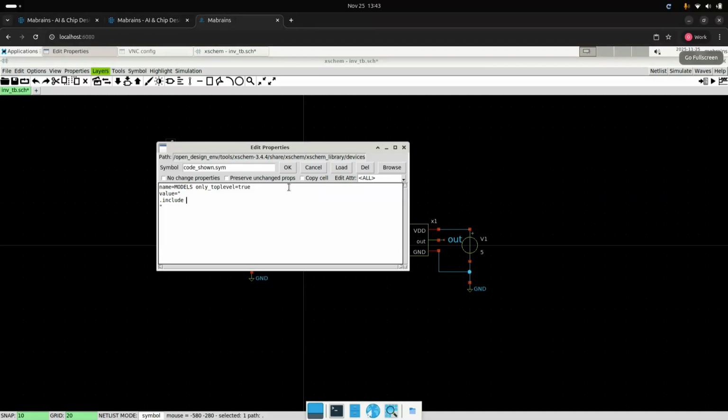How you do that, you can use our predefined variables. So you write $ and you define our PDK path. This is the variable we defined before. This is a combination of the PDK root plus the PDK variable. So you use the PDK path and you go to libs.tech, then you go to ngSpice, and then you go to the design.ngSpice file.